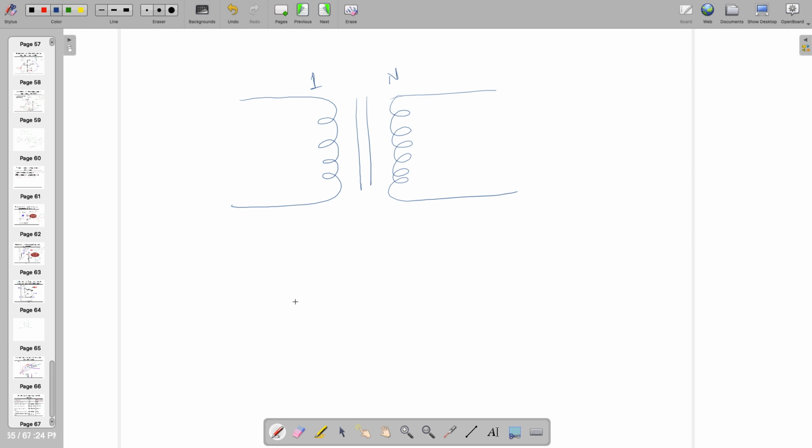Whereas in an amplifier, what we want is, for any value of resistance, I want V out much larger than V in. This is what we are going to call an amplifier. Not only from such a configuration where by changing the resistance value, it's changing, and that's why we want that for any voltage-controlled voltage source amplifier, R out is as low as possible. So for zero resistance itself, I want to see the amplification, and zero resistance is not possible. For standard practice, we can call it 50 ohm.